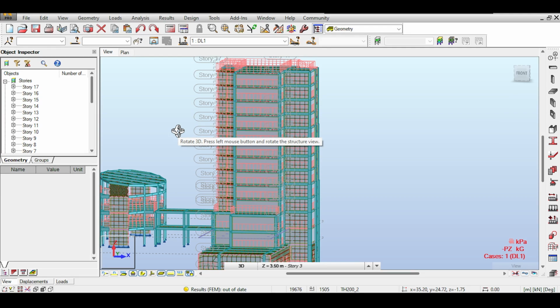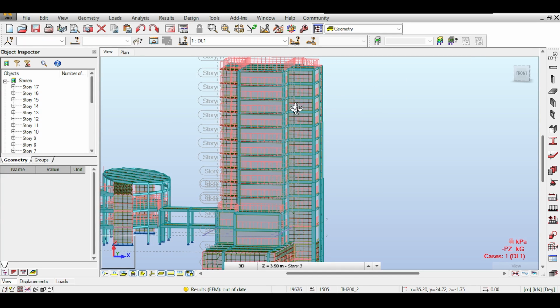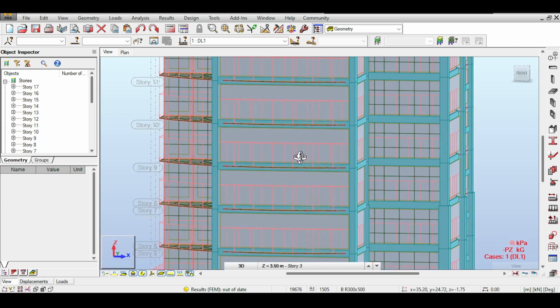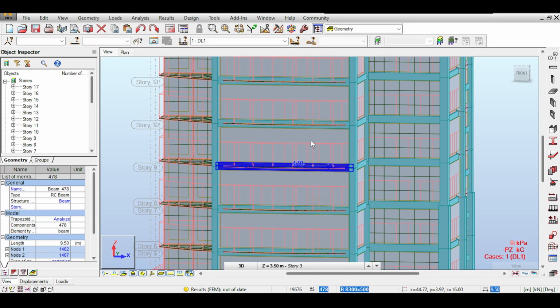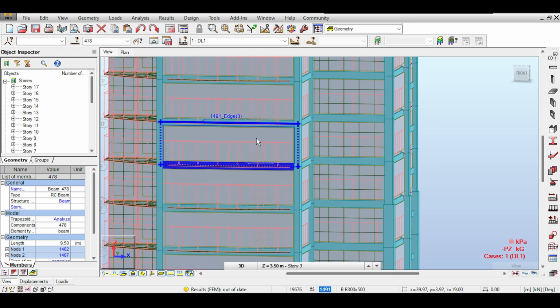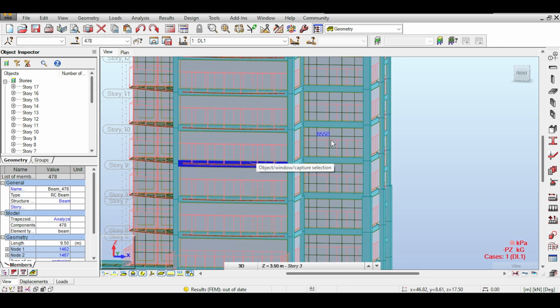As for the beams, it's a tad different, because changing the section of a beam also changes the loads or the moments transferred to the column. You see, you should have a strong column, weak beam scenario, where the column is stronger than the beam. This is basically one design concept that was not followed in Turkey, and we all know what happened during that earthquake. I have covered it on the top right. Check that video out. But the beams are a little bit different. I need to make them a little bit weaker than the column. And the controlling factor for my beam design in my iterative scheme is to make sure that I am not going over the deflection ratio.